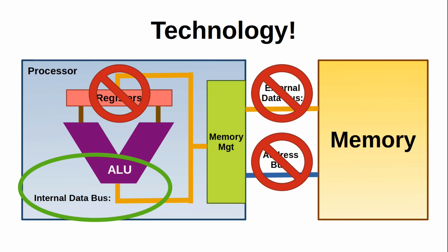But that instruction is actually running through an ALU that's only 8 bits wide. And so it's actually doing two adds. And that's why it takes so long. If it was an actual 16-bit processor, it would just have to crank through that ALU one time instead of cranking through it twice and handling all the carries and all of that. You wouldn't have to do that if it were an actual 16-bit CPU.